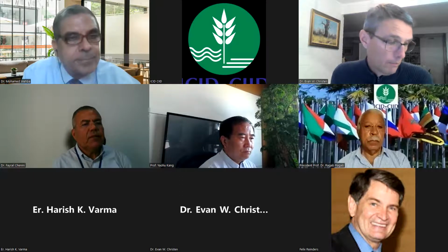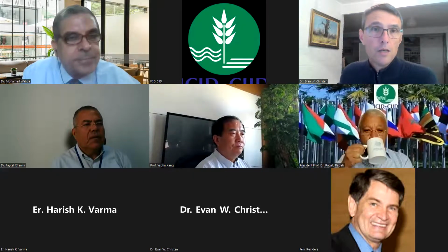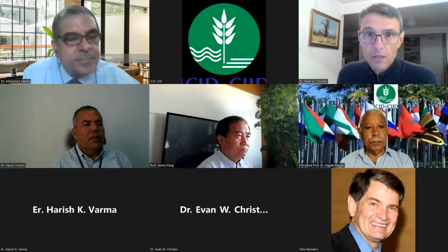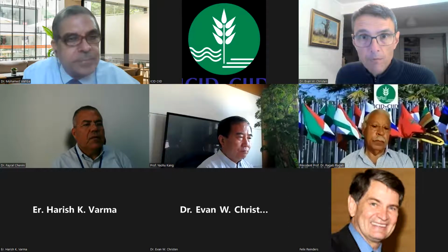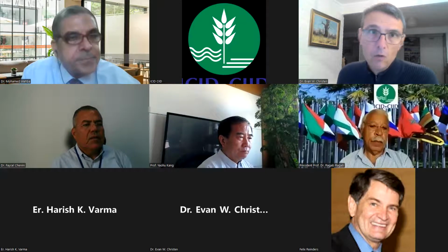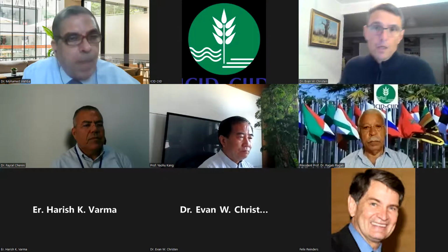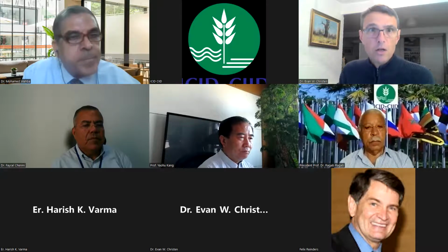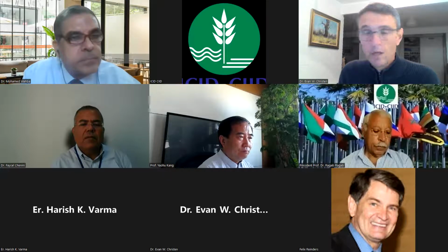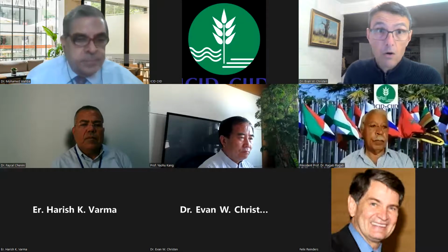So you get a kind of traffic light indication, and the work of Dr. Kang is exactly right, that the optimum soil water potentials are generally around 20 kPa, not wanting it to get too wet, probably not less than 10 kPa, and not wanting it more than 50 kPa. So that 20 to 50 is, Professor Kang's work has shown that very clearly, very suitable. So the kind of tools we have developing, providing that in a color scheme, is much easier for farmers to interpret and can be logged over time as well.